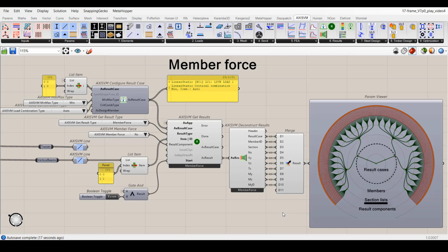These sub-branches contain the section positions in the local coordinate system of the member as data lists. Similar to what we saw at the nodal displacement, we have more values in a common branch. For the section lists of each finite element, we have the already mentioned 7 sub-branches for the result components. Similar data structure is used for line and member displacement, line internal force, and line support reaction force as well.